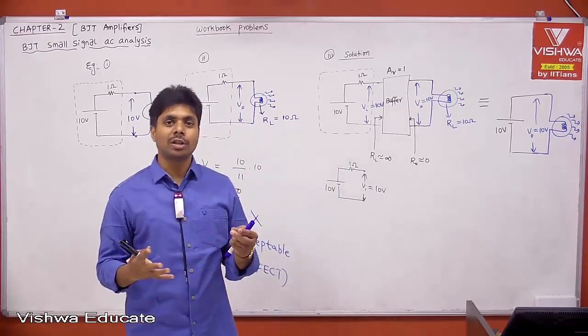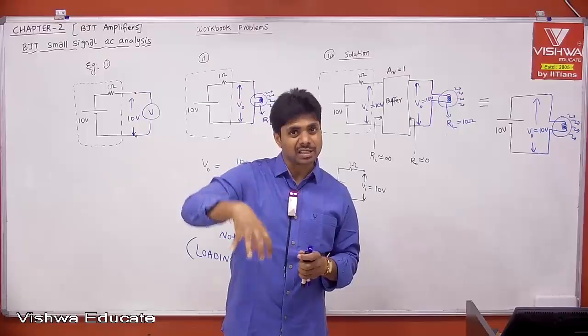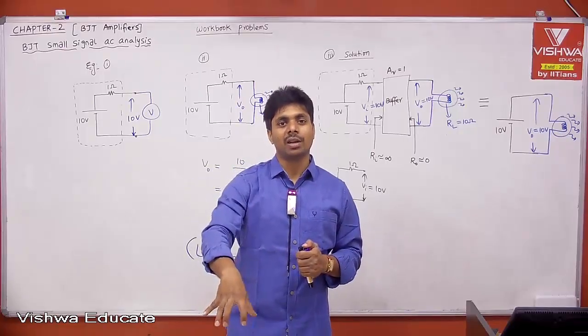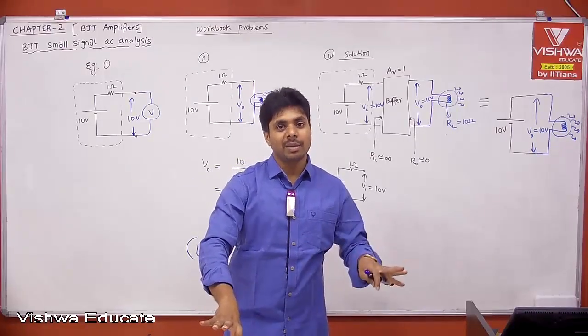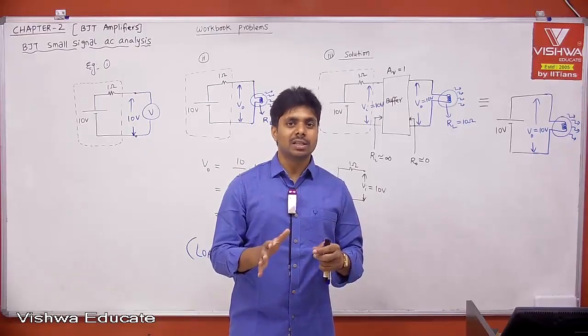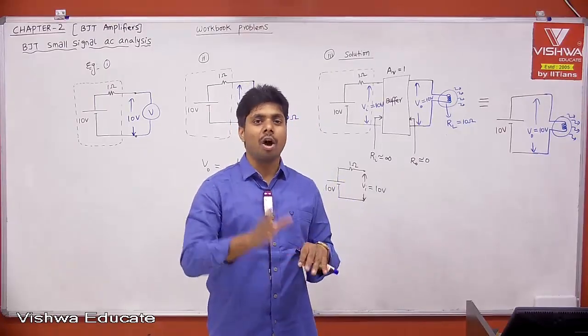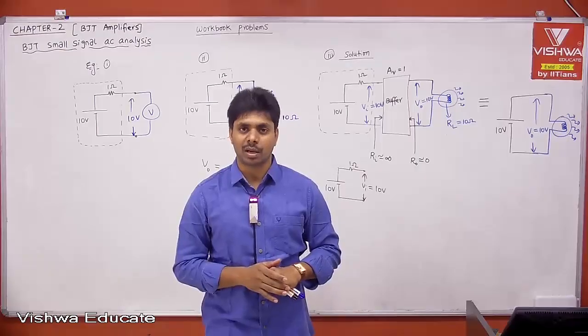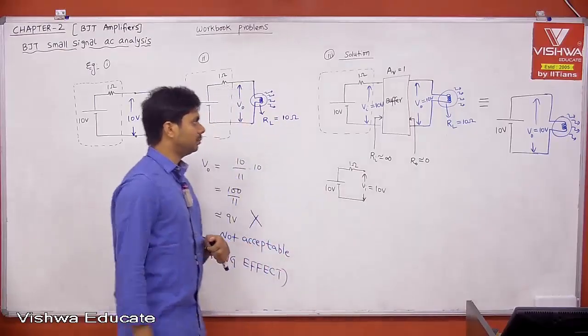Okay. Therefore, we are going to take the specialty of each circuit. Therefore, from CC amplifier, impedance matching. From CE amplifier, voltage gain. If you combine, you will get the best amplifier. See, slowly we are trying to get the op-amp internal block diagram. Right? Take it.